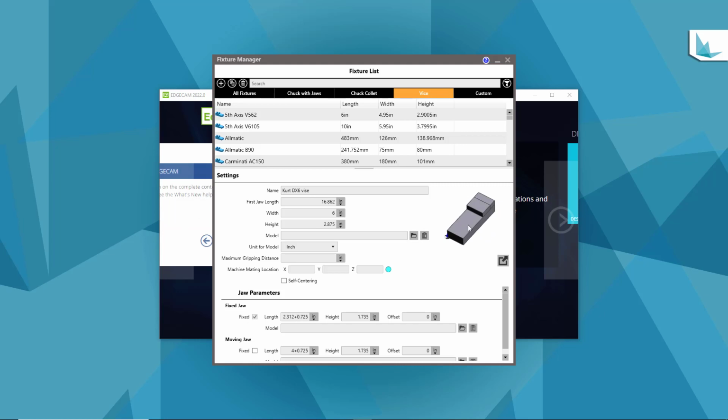I want to note that it's always important to start with parametric graphics, and in some cases those are going to be enough to describe the item for you. But it's also a good starting point even if you're using solid graphics. In this case, it helps me show you that the starting point or go position for solid graphics needs to look like the parametric graphic, where the jaws are completely closed in that closed position.